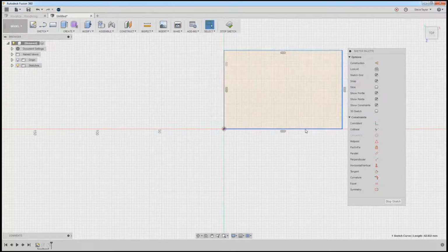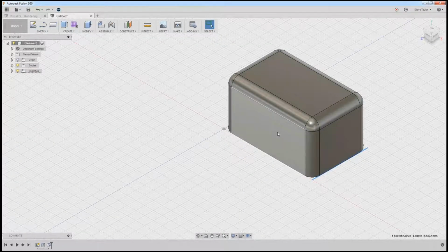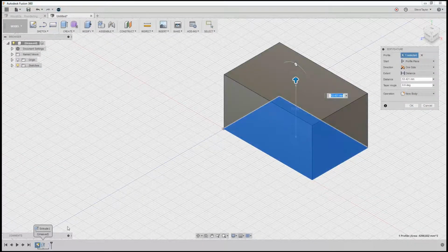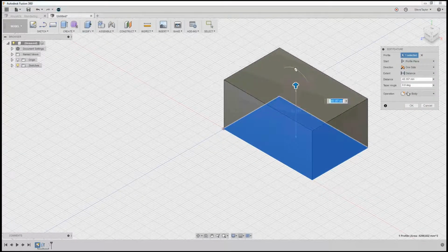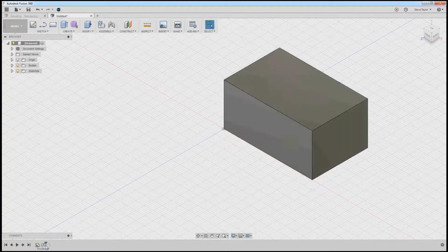I'm not putting any dimensions in at the moment, I'm just pulling and stretching, stop sketch, and it will update it. And it's the same with the extrusion. Again, straight back into it. I can manipulate, I can put my sizes in, press OK. And at the end of it, I can actually drag this marker right to the beginning of my timeline.